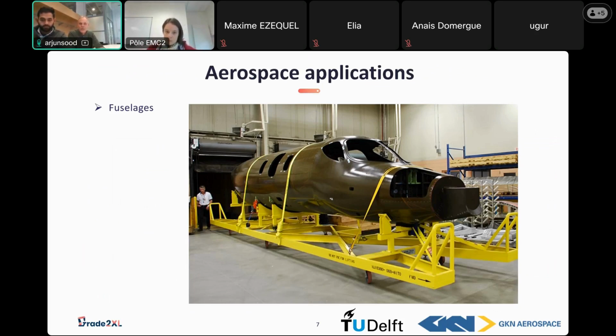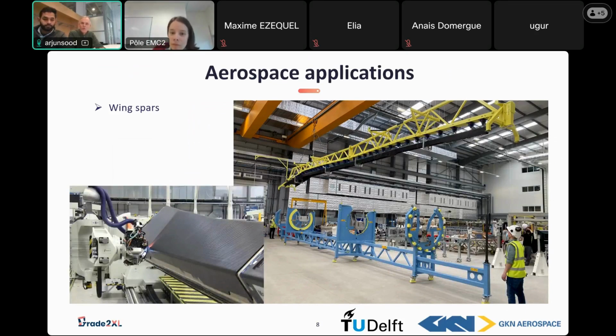Next slide, please. This is for making wing spars or spars for tails. On the big picture, you see a 17-meter long spar which came out of a double-sided tooling. On the left picture, you see an automated layup of such a piece on top of a mandrel that's made of INVAR material, because for these kinds of sizes, we typically use INVAR material, and I will explain a little bit about why we are doing it later.